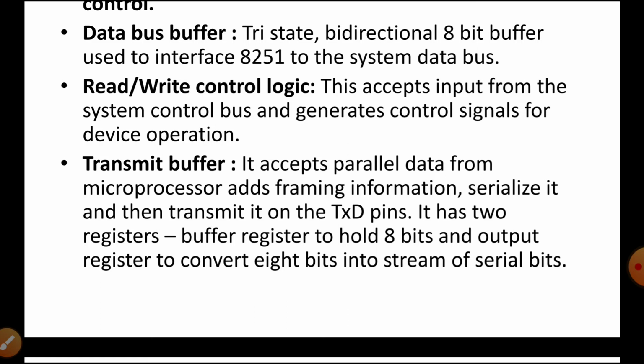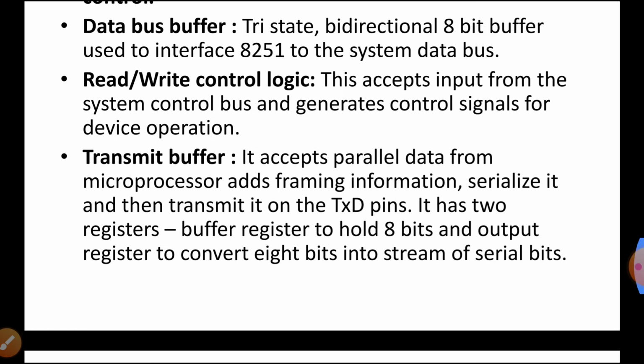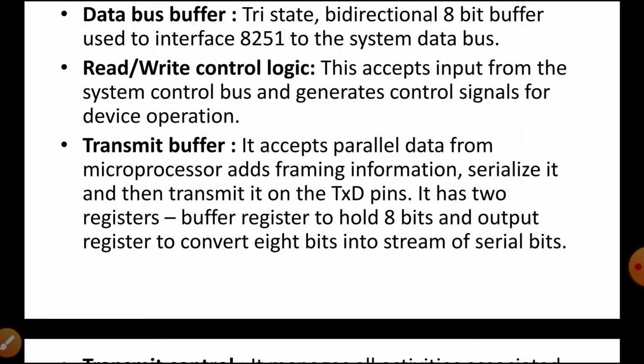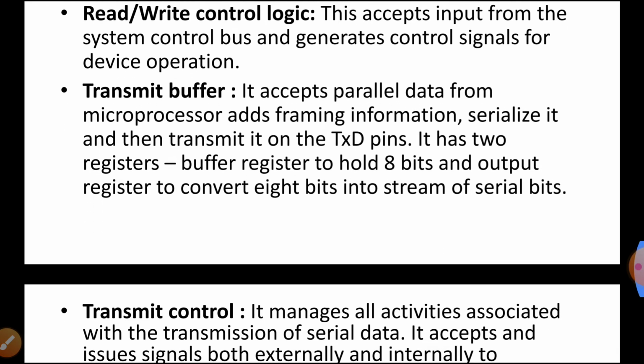Now, in asynchronous mode of data transmission, the transmitter always adds start bits, depending upon how the unit is programmed. It also adds an optional even or odd parity bit, and either 1, 1.5 or 2 stop bits, but in synchronous mode no extra bits are generated by the transmitter.